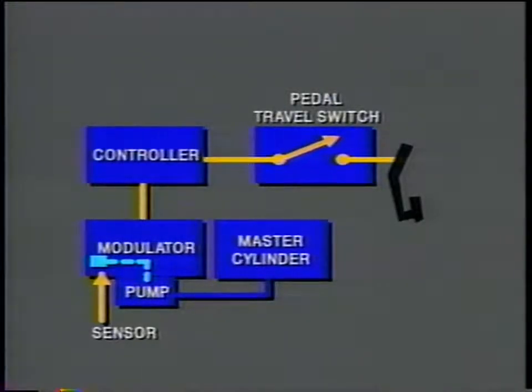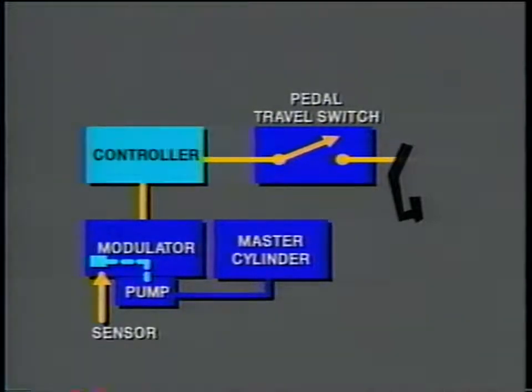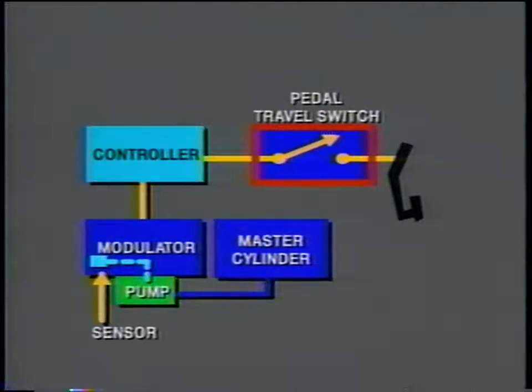There's also a pump motor sensor in the modulator assembly that signals the controller when the pump is running. If the pump runs excessively and the brake pedal switch remains open, the controller recognizes that something is amiss and sets a fault code.